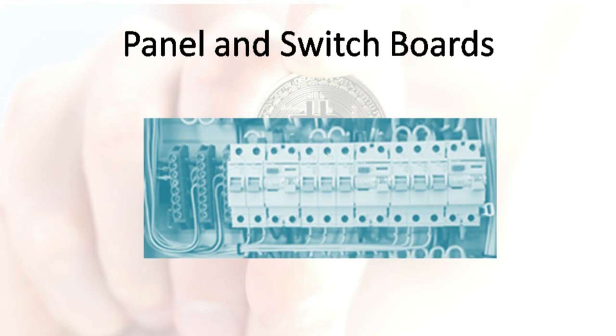It is an assembly of one or more panels, each containing switches that allow for the redirection of electricity. Now, a switchboard's function is to allow for further diffusion of the current supplied to the switchboard into smaller currents and to provide switching, current safety, and possibly metering for these different currents. Switchboards will typically distribute power to transformers, panel boards, control equipment, and to individual system loads.